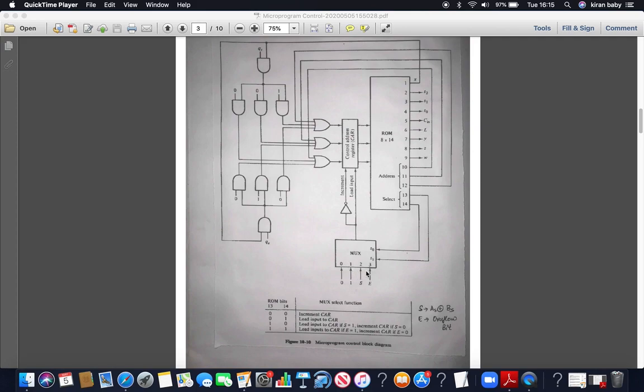Okay. Now if the mux value selected is 2, that is, if the selection bits are 10, then this line 2 is enabled and S is enabled. This S is nothing but the output of the XOR operation of the sign bit register AS and the sign bit register BS. I hope you remember it from the previous video. If there are two registers A and B used to perform an addition or subtraction, their sign bits are stored in registers AS and BS.